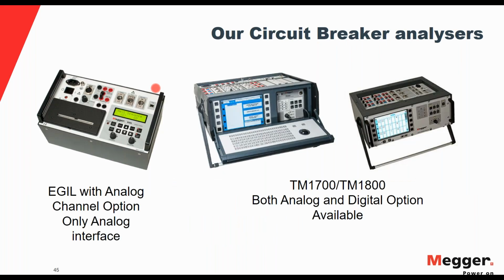So a lot of these transducers, either analog or digital, can be used with our advanced circuit breaker analyzer, the TM1700 or 1800. If you have the EGL unit, which is more designed for the medium voltage breakers, make sure you have the analog option. It has the motion transducer input to connect the transducer to be able to capture this measurement.